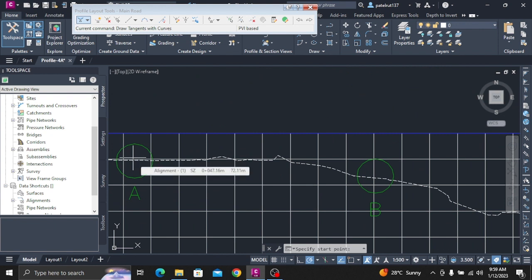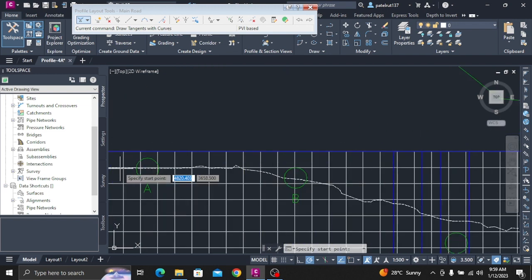Click Next. On the Data Bands page, under Select Band Set, select EG-FG Elevations and Stations. Click Next to open the Profile Hatch Options page. You can use this page to specify hatch patterns between the profiles in the profile view. For this exercise, you will not specify any hatch patterns. Click Next. On the Multiple Plot Options page, set maximum in a row to 4.